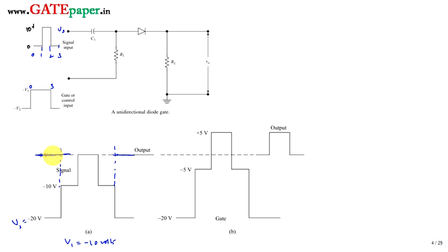And even during the transmission path, by that time you are applying minus 10 volts plus 10 volts, the voltage at this P side is going to be 0, so you don't get any output. Even though you are applying an input signal, the output will be 0 only. So no transmission is taking place. That's why V1 should not be a negative value, and here we have taken it as a large negative value. It should not be this way. V1 of minus 10 volts takes the entire 10 volts of the input signal, so that the effective voltage is 0 volts.